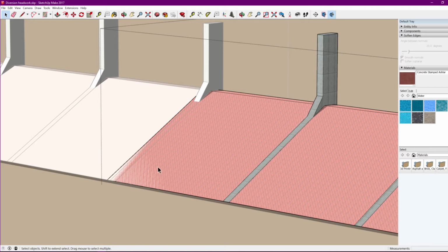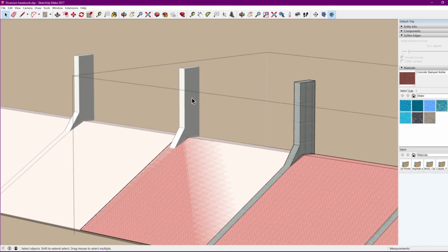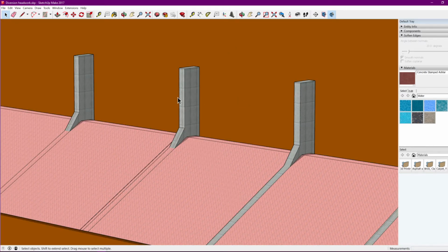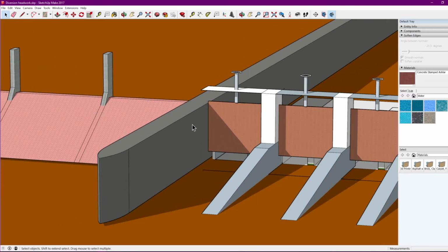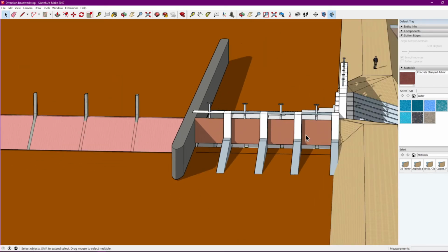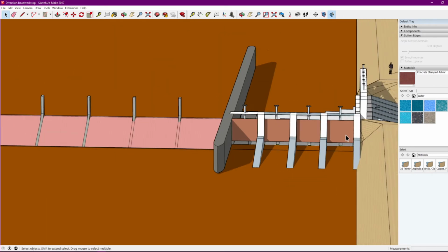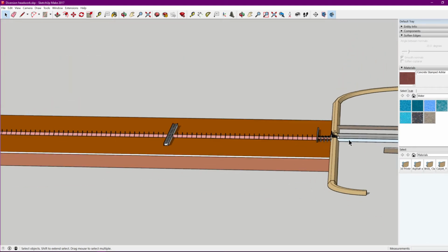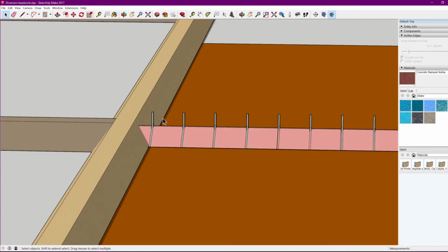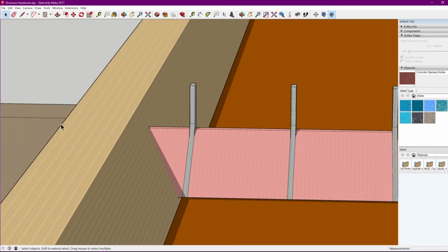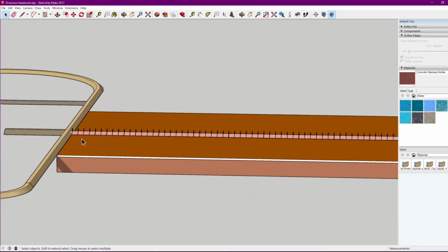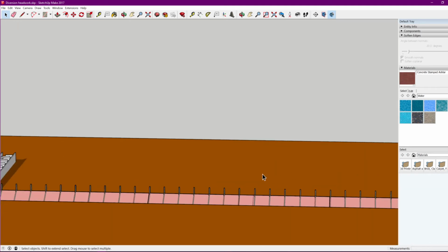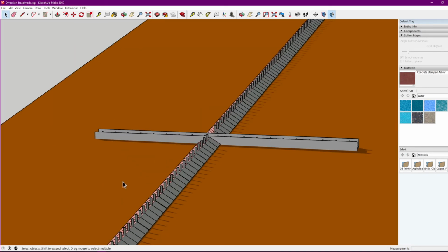That means the bottom will be at least at the same level as the riverbed, and here we will provide some gates, just like we have provided in this region. That means in a barrage, instead of only a portion of this thing being gated, the entire length from here up to here will consist of only gates, and all those gates will be opened or closed based on need to store water or release water. So we'll discuss this whole thing in much greater detail later on.